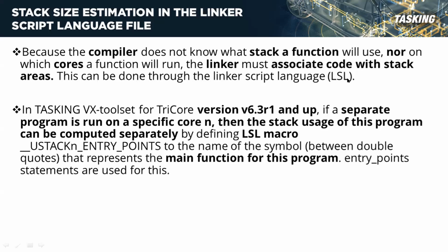You could change the linker script file in order to measure the stack size. And how could you do this? You could use something called LSL macros. The LSL macros are basically normal macros that the linker is aware of. If you configure this, you are telling the linker to take care of measuring the stack size for certain functions.